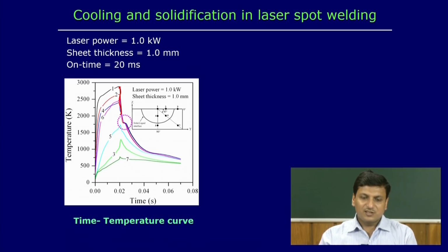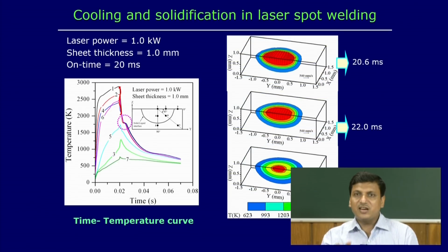So, in the case of an alloy, this phase transformation from the liquid phase to the solid phase happens between the solidus and liquidus temperature. That is why we get this kind of hump here. It indicates that phase transformation happens during this process, and it also signifies that in this numerical model we can incorporate the effect of the phase transformation.